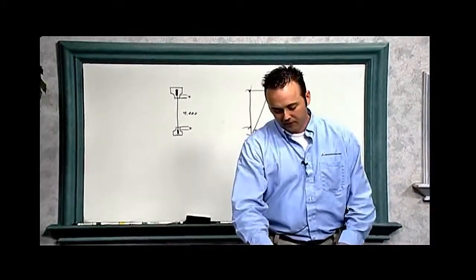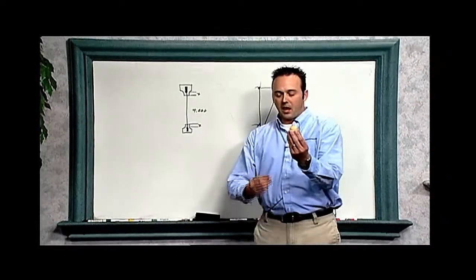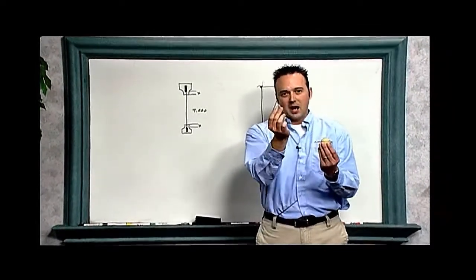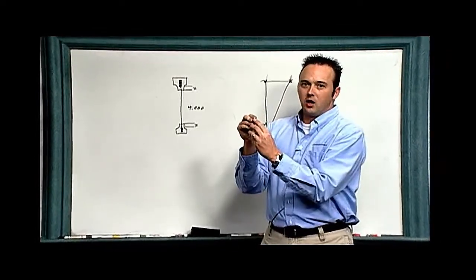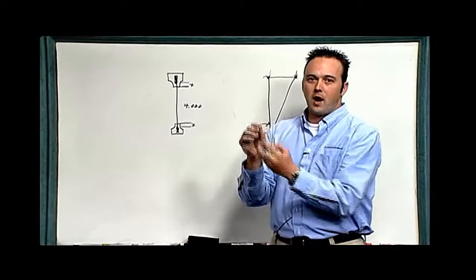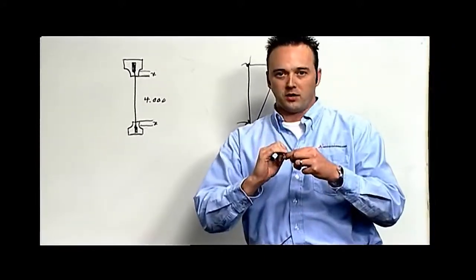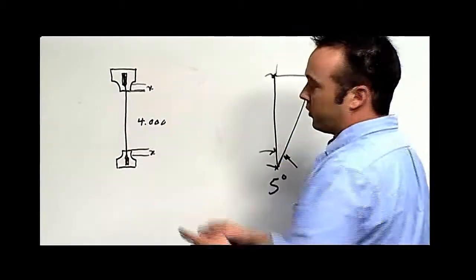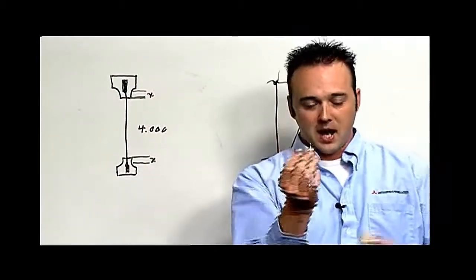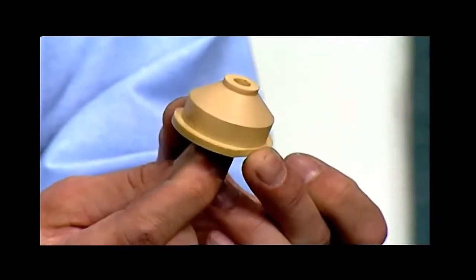So what we have on both upper and lower heads will be a flush cup, and inside that flush cup is the actual diamond guide. And in the very top of this diamond guide, there is a ceramic cone where the wire pivots back and forth. Well, it's the pivot points of these diamond guides that I need to know the span between in the upper and lower, because this diamond guide is inserted inside the upper flush cup assembly.